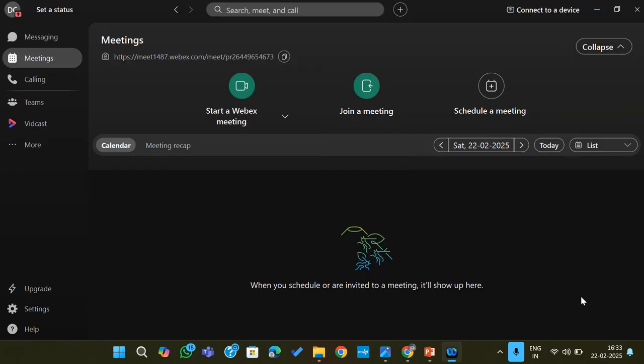Inertia friction welding. Inertia means there will be a flywheel. Once the motor starts the flywheel, the motor will be stopped after some time. Then the flywheel will keep on rotating to make the weld. So initially we are giving the maximum speed, then we are stopping it. That is clearly shown in the video which I have played, for joining very big cylinder components. When you play the video, you can understand that.